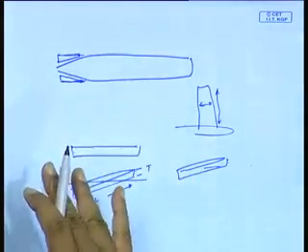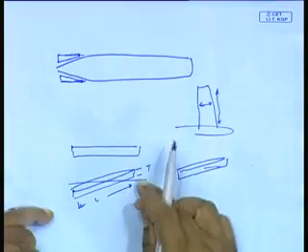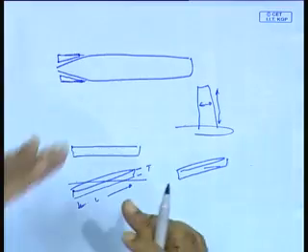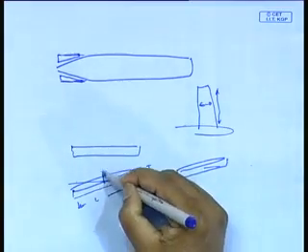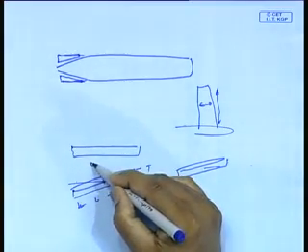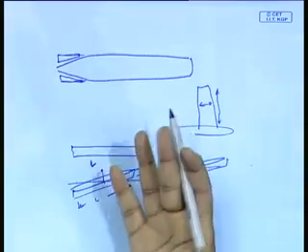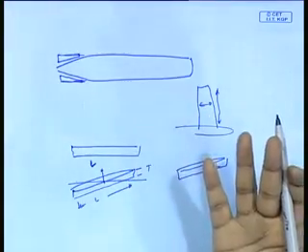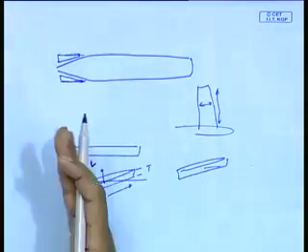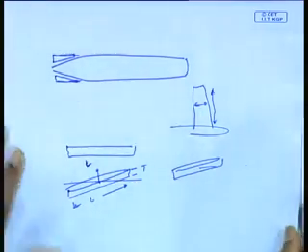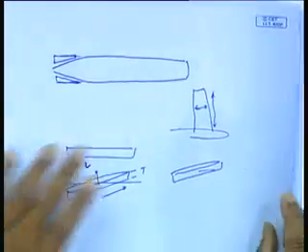We will find out, as I said, that you can make estimates of hydrodynamic derivatives assuming the ship to be a low aspect ratio lifting surface, and the lifting force that you get, C L, is connected to my y forces. Essentially we will be seeing that later on. So that is why low aspect ratio is important, and I just want to mention these points.